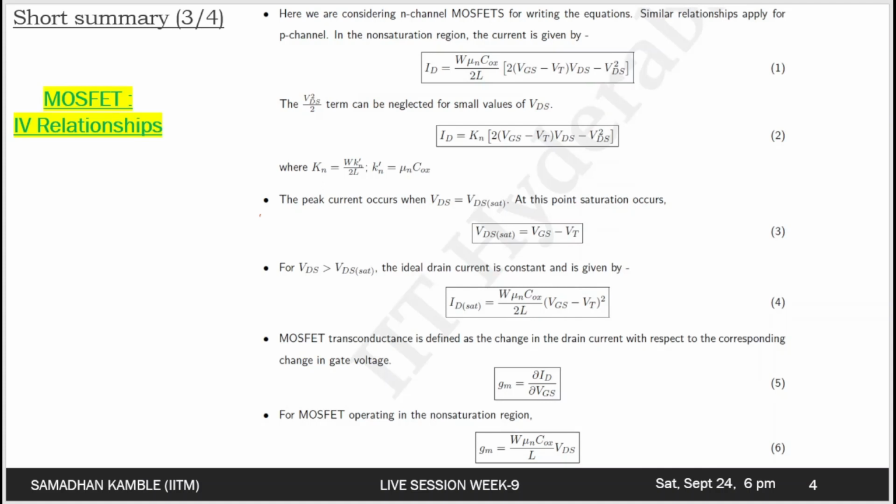So to summarize, this week was basically devoted to understanding the physics and characteristics of the MOSFET. The MOS structure was assumed to be ideal, and considerations were limited to the basic transistor configuration only. And when a MOSFET is biased into the inversion region, the induced surface layer forms a conducting channel between the source and drain contacts, as I mentioned in slide number 1.